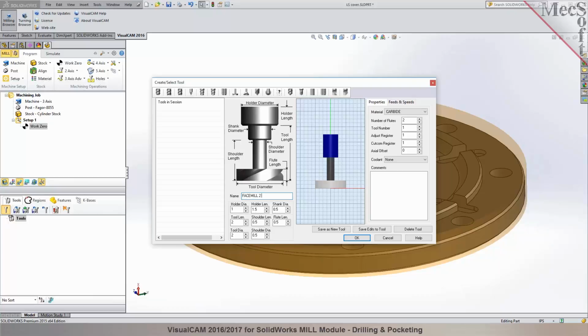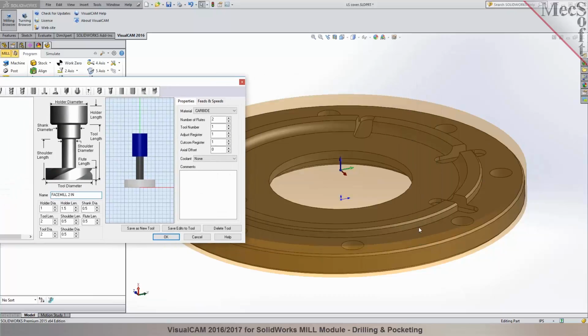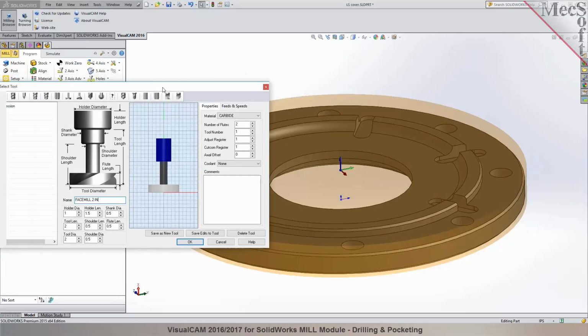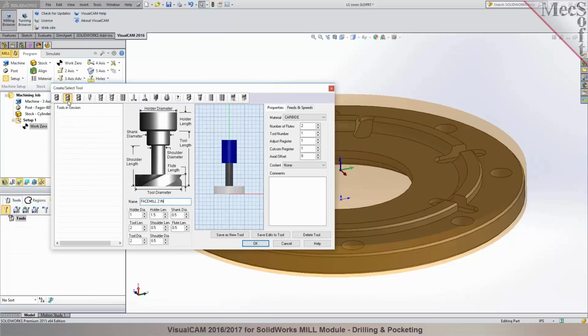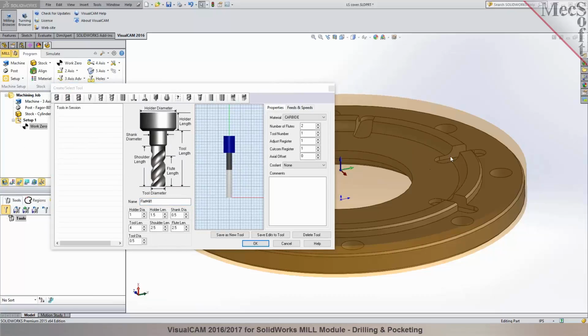Okay, I'm sorry, but we were thinking about turning the part and milling only the slots and drilling the holes. Okay, all right. So if you're looking to just do the slots and drilling the holes, we can do that in here. So let's go ahead and change the tool type in here. Do you know what size end mill you would need for the slots?